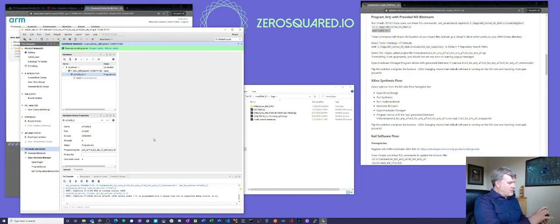And it looks done. Once it's done, you should be able to flip the switches and push the buttons and see the LEDs light up. And once you look at the block diagram, you can see that the switches and the LEDs are interrupt driven. So if you flip a switch and the LED turns on, then you know that you successfully triggered an interrupt and the processor core handled that interrupt and set your LED, and so you know that it's up and running software. So now we've tested out the first part of our flow.